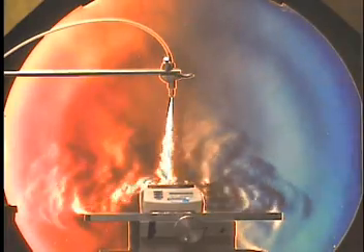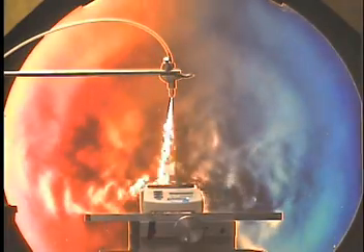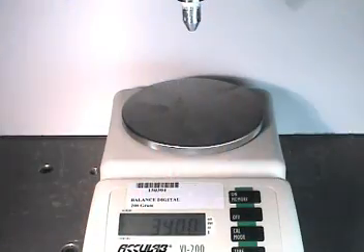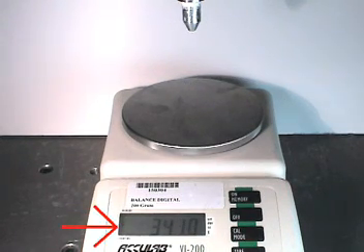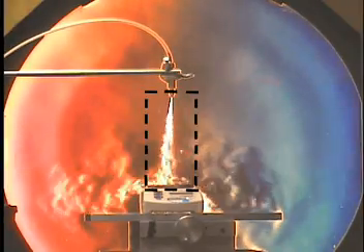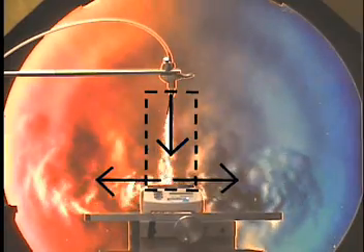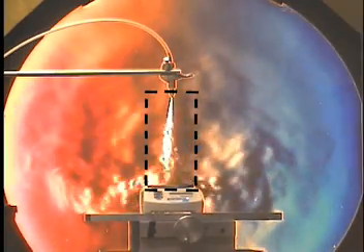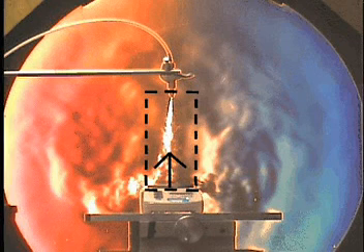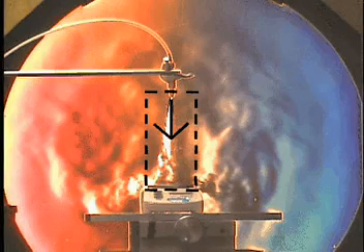Here, a jet of shop air impinges on a scale. We can see the airflow using the Schlieren optical method. The air jet impinging on the scale produces a measurable force, shown by the digital readout, since all of its momentum is transferred to the plate on the scale. Here's an appropriate control volume to analyze this process. A sum of the forces and the momentum fluxes in the vertical direction, using the Reynolds transport theorem and Newton's second law of motion, reveals that the reaction force measured by the scale is simply equal to the momentum flux coming out of the nozzle.